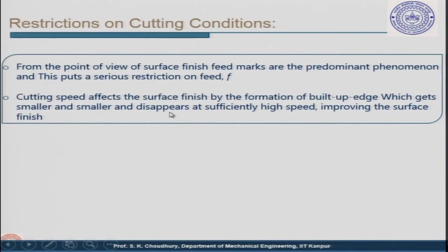Cutting speed affects the surface finish by the formation of the built up edge, which gets smaller and disappears at sufficiently high speed when the temperature goes beyond the temperature of recrystallization, and then the surface finish improves. So, these are the two points which are important here.